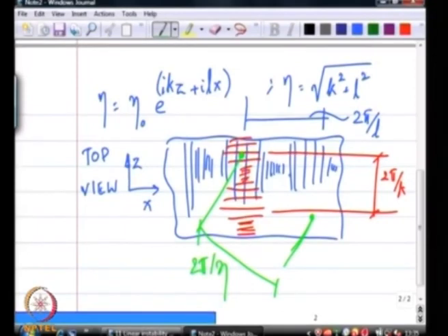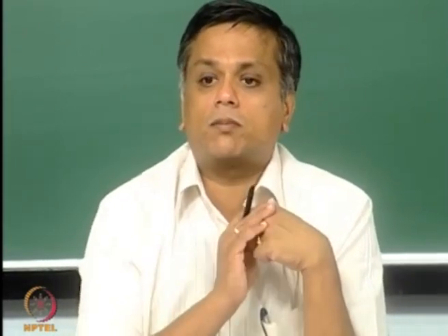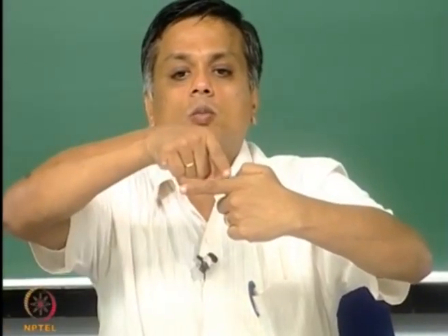So, this combination of these two waves is going to look like waves of wavelength 2 pi over eta in the direction given by tan inverse L over k, or tan inverse k over L. However, the velocity direction is still x. So, it is like I have a velocity direction x, but I have chosen to superpose waves in some other arbitrary direction. That is the only result of having two wave numbers in directions along the flow direction and perpendicular to the flow direction.